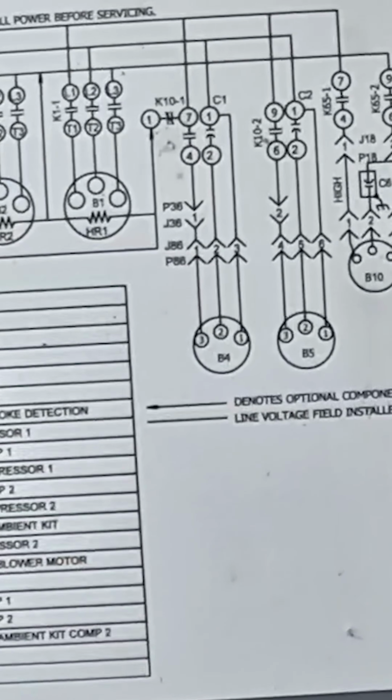Connect the sensor on air supply, smoke detector only. So just always be mindful of that if you're looking in the vicinity. Like there's a number 4 note right here on that blower motor. Right here's number 4: S42 used on M voltage units and units with high efficiency motors. S42 is an overload relay blower motor switch.